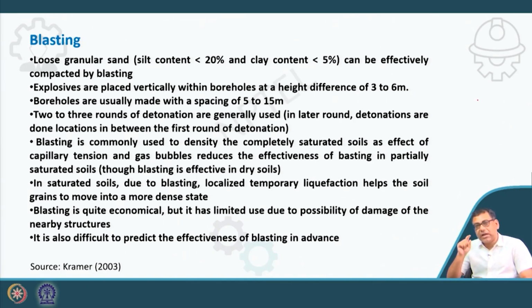So that means the blasting should be done either for completely saturated or dry soil, because if it is partially saturated, then it is not that effective due to the presence of capillary tension or gas bubbles. Okay, so if we go for saturated soil, due to blasting, localized temporary liquefaction helps the soil grains to move into a more dense state. Okay.